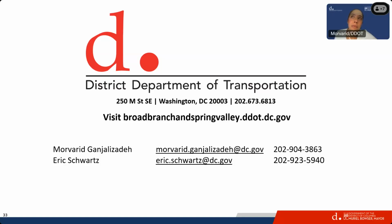With these, the design of the facilities is supposed to be a little bit below the street level. One of the big things that these do is they collect runoff from the roadway and then have ponding on top of the soil. That's part of where we get our treatment volume from, because that can pond and then sink in to be filtered through the soil. The other thing is bioretention planters are really not supposed to be walked on. It's non-compacted soil in there, which increases the amount of voids so that the soil can hold more water, and it's better for vegetation, which improves the treatment quality and the vegetation life.